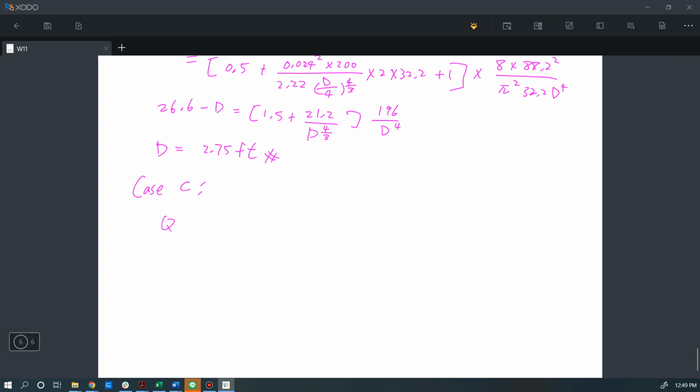We will use this equation. We have also shown this example for case C in a previous problem. Here we follow the same steps, and the h here is the distance to the center of the culvert, so we need to subtract D divided by 2.